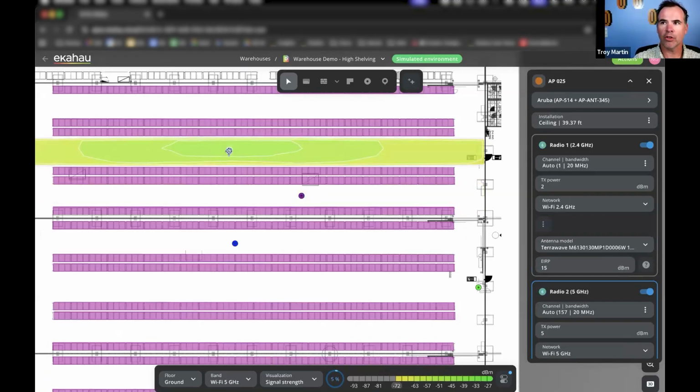So related to that question, you mentioned earlier that at 25 feet, that's sort of your tipping point to start looking at directional antennas. Yes. Just made the comment that the ideal spot was sort of 35 feet. So my question is, is there a range that's too high? Is there a ceiling height or a distance that you're trying to shoot where you'd feel uncomfortable, and think maybe we should find a better position for the antenna that we can get closer to the client?